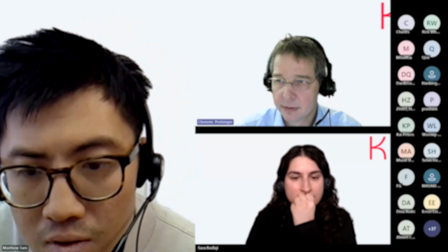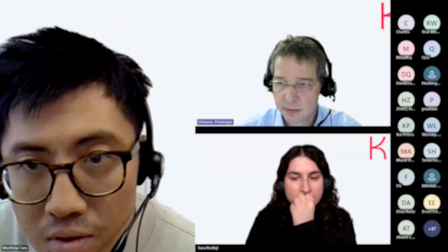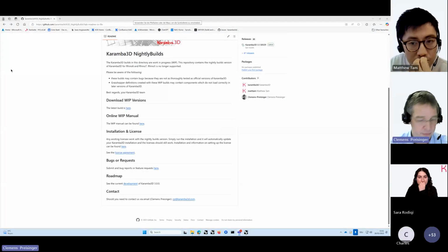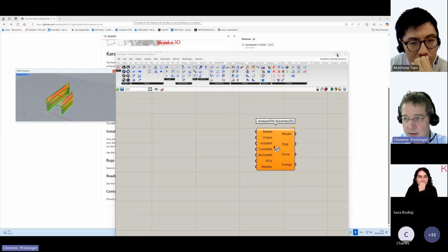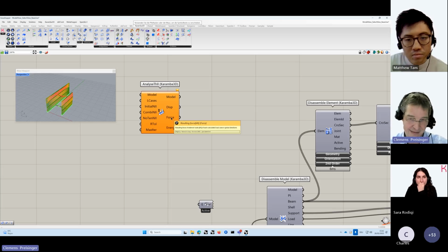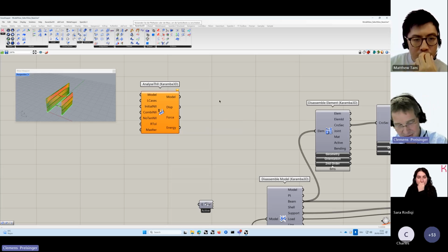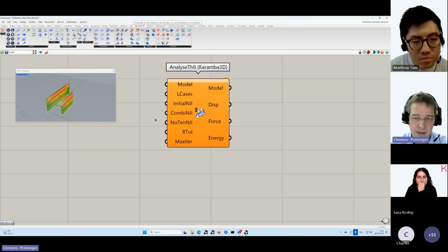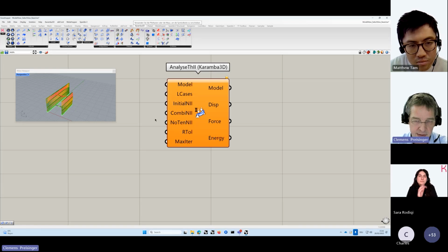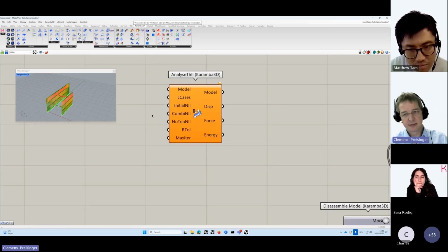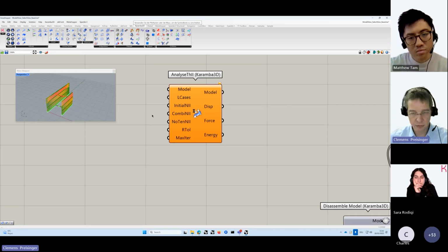Well, let me again share my screen here. The cross-section optimization consists of two parts. The first part is to ensure that the ultimate limit state is adhered to, so that the structure doesn't collapse. And the second step is to ensure that the deflections are not excessive. And in case of the ULS, the ultimate limit state iteration, buckling is included.